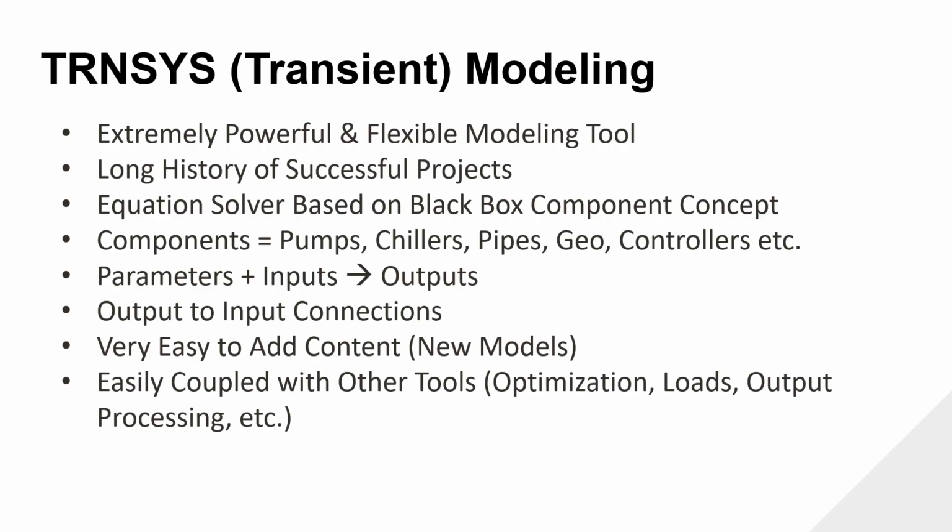And what we found is that TRNSYS is really basically building a digital twin. So we're really putting together the pumps, wires, and pipes as you would in the real world. You would go build it; we build it in a software platform. And similar to Modelica, you can operate that and look at any point in the system on 15-second intervals and see how the system is operating. And then you can optimize from there by changing control sequences and dispatch models.